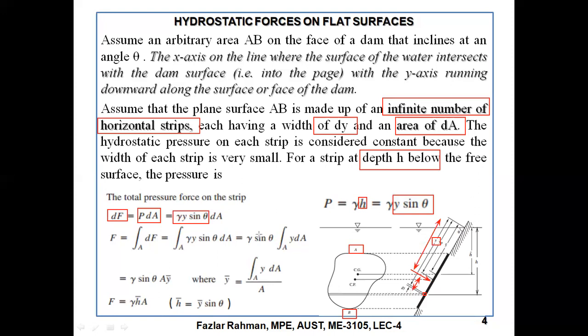That's why in the integration we bring gamma sine theta out of the integral, and the remaining term is the area integration of y dA.